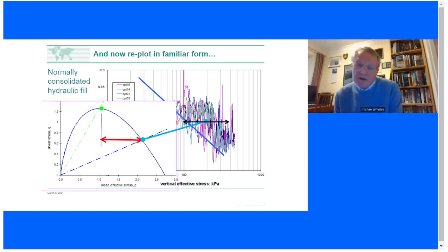That means that I've got a lot of yield surfaces here, and the yield surfaces are moving around, because the line I've drawn in light blue, the two endpoints, they're one and the same place. So what we have here, we see from CPT testing that that green dot is not the critical state. So this was the issue with Cam clay. It's not really an error, they made an unnecessary assumption. And this insight came out of careful cone penetration testing on a hydraulic fill. And this insight is the origin of NorSand.